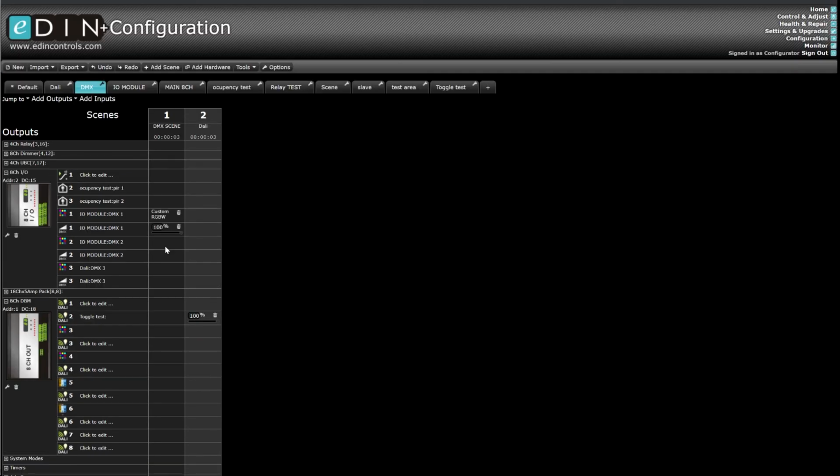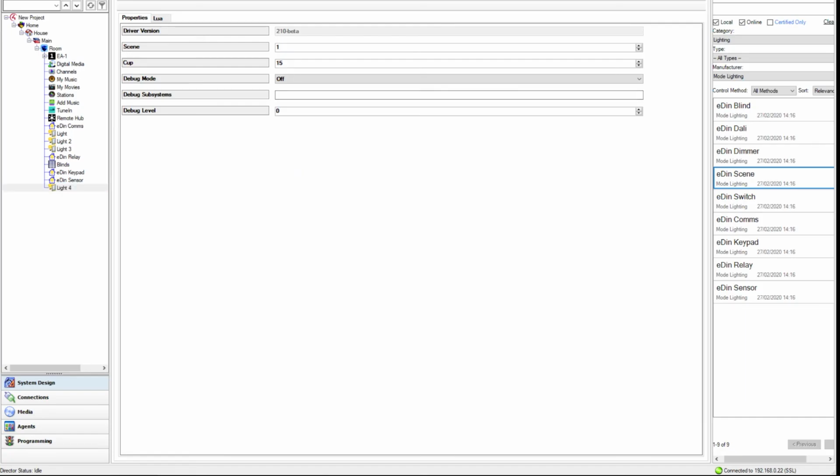that I've made up. To find out that scene number, I hover over the top here, and in this case I can see it's $scene recall 37, so it's scene 37. I come back through into our Control4, pick 37, and hit set. Now that's set up correctly. Usually this is needed so that you can have the scenes that have already been set up in the MPU controlled from Control4. There are a few extra steps that are usually done.